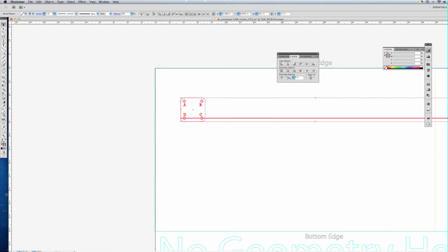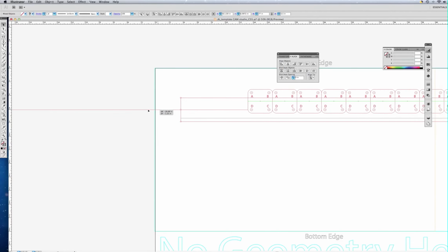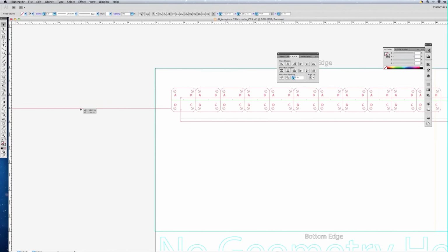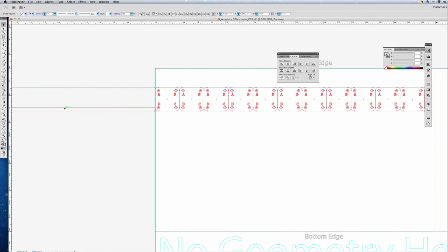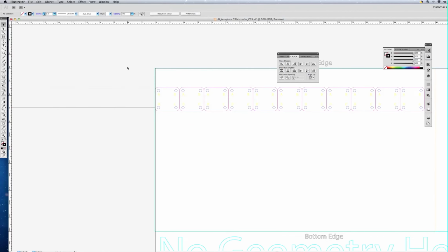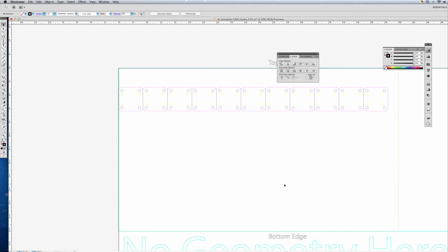We want to click on horizontal distribution, and you'll all of a sudden see like, oh, where'd the tablets go? They're there. However, if we click on the selected items, hold and drag, we'll find that they're further to the right. Once you release it, it sets it into place. You can click anywhere to deselect, and then we want to erase our reference line. So we'll select that and hit delete on our keyboard. So now we have quite a few tablets, and they fit pretty good within the space of our material.